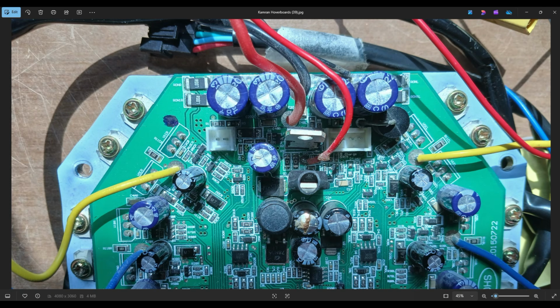I'm not going into that much detail. Simply, R007 means 7 milliohm for the shunt resistors, and two in parallel give 3.5 milliohm. A single R007 gets hot at 30 ampere. This is the other setting, very simple. Two shunts means it is measuring two phases, and from those two phases the third phase is calculated. The rule is A plus B plus C equals 0.